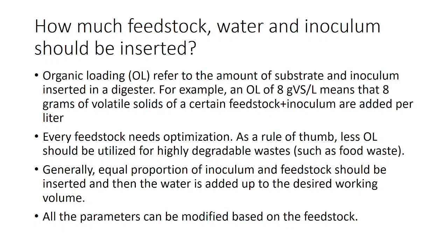So a simple question arises: how much feedstock, water, or inoculum should be inserted? For that, first you need to know the term organic loading. Organic loading means how much substrate and inoculum will be inserted, because these are organic matter which will be present in your digesters. Mostly for the organic loading of solid feedstocks, the weight based on volatile solids is used.